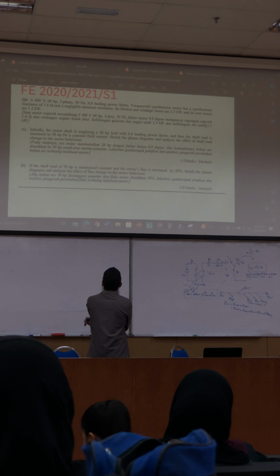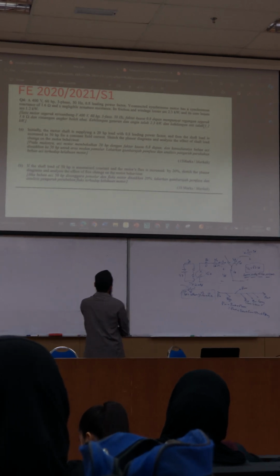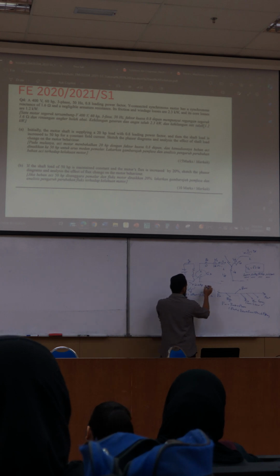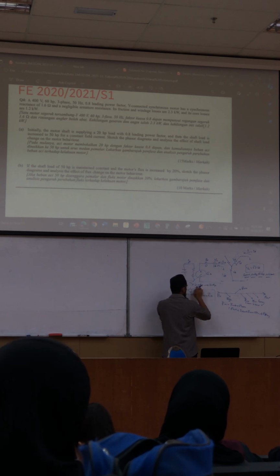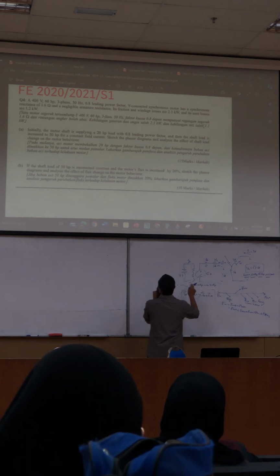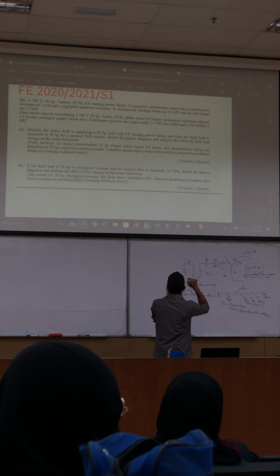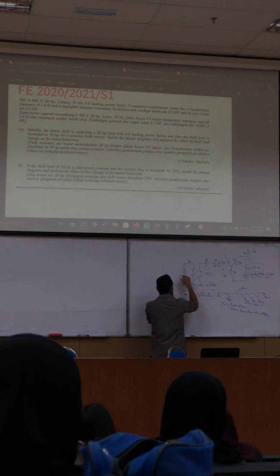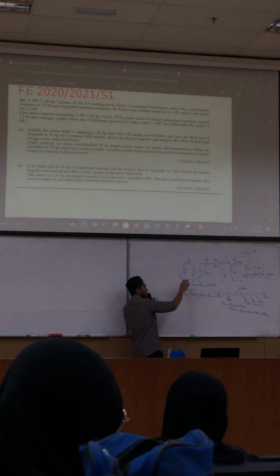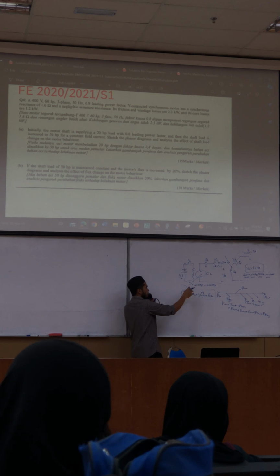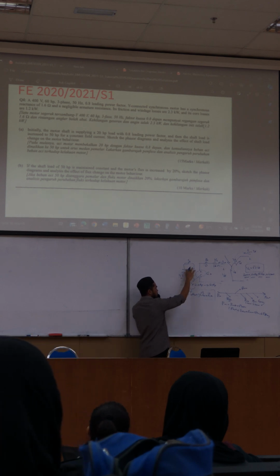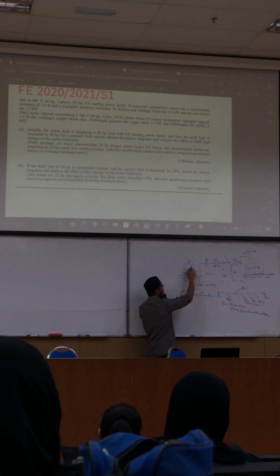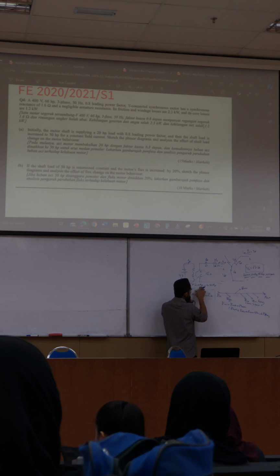Start with 20 horsepower, then increase to 50 horsepower, with the condition that field current is constant. Field current is constant, it does not change. So you fix your V_F, you just add load. What happens here? The magnetic field is steady state and does not change, even though the burden increases from 20 horsepower to 50 horsepower.